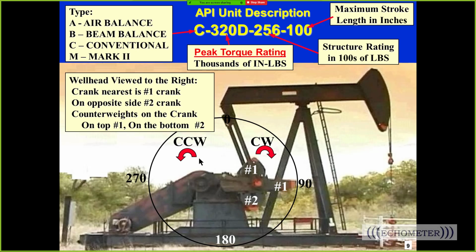Now this is a conventional pump unit, and we have our panel back here at the back, typically where we would attach the power probes. This is our electric motor that we're able to simulate the kW into from our power input to the system, and we're going to use that to analyze the net torque on the gearbox and some other parameters we'll talk about.